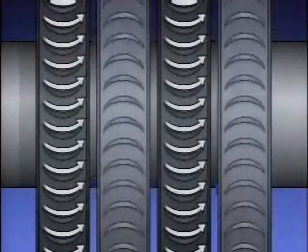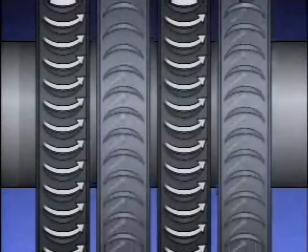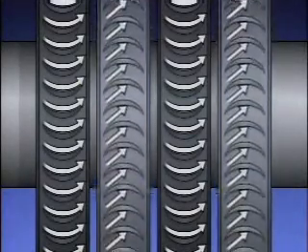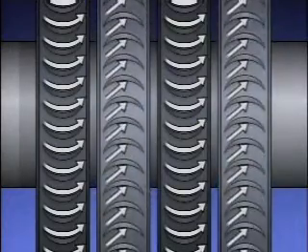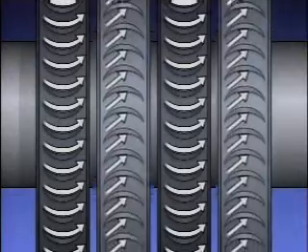As high-pressure steam is forced through the stationary blades of a diaphragm, it speeds up. The steam striking the rotating blades causes the wheel to turn. Since the wheel is attached to the shaft, the shaft also rotates. Reaction blades work differently. With reaction blading, the speed of the steam's movement causes the rotating blades to turn.